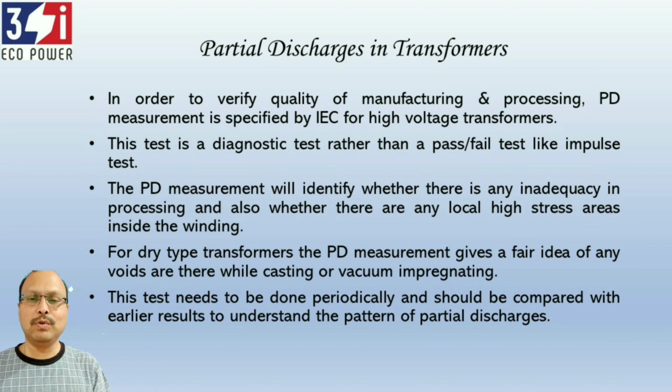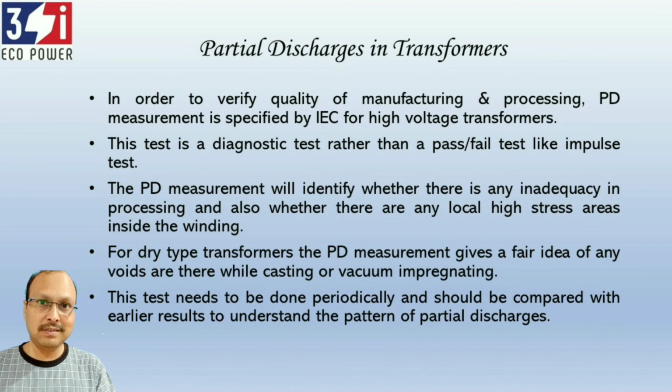This test is really good to understand the adequacy of the insulation system, or how the insulation system is performing over a period of time. So this is basically a diagnostic test. For dry type transformers, it can tell how the casting is, whether there are any voids or gaps while casting.